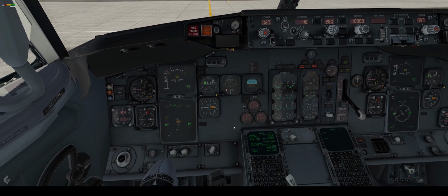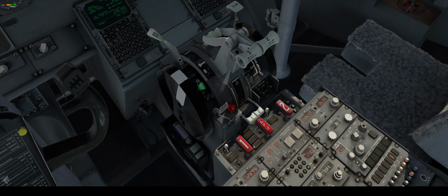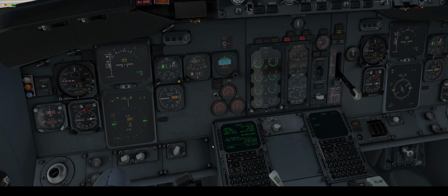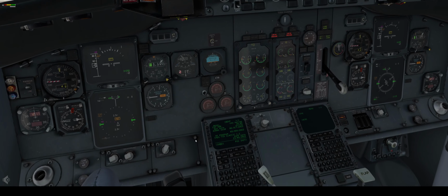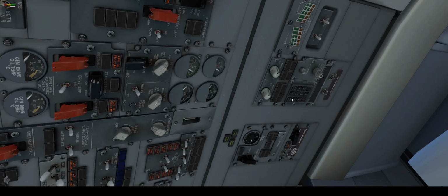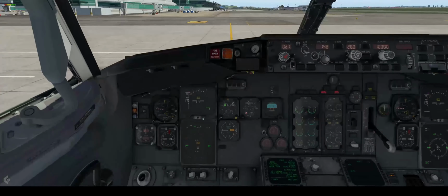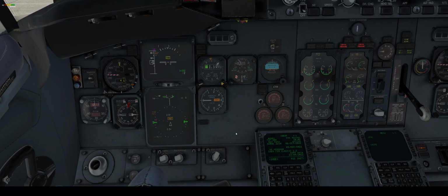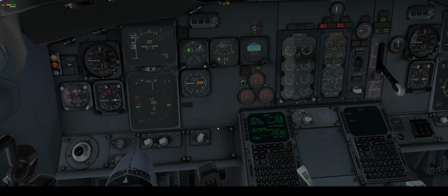Because I see on IXEG, but it's a fail from my side, it offers you to make an RNP approach. To make an RNP approach is impossible unless you have GPS installed in the Classics, and you have the proper software in order to make these waypoints workable. So that's it. But basically the basic idea of the FMC is the same.